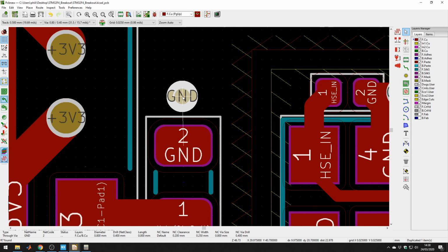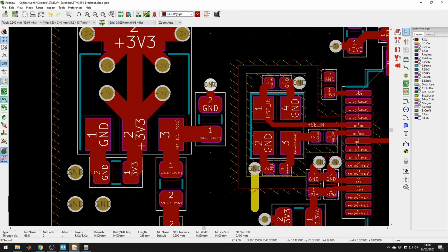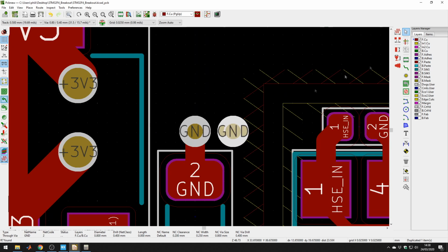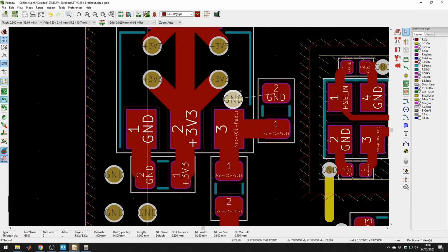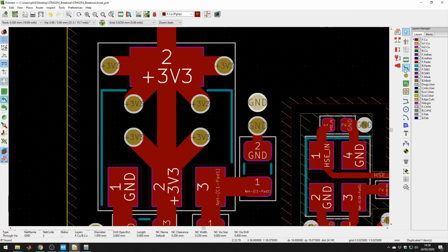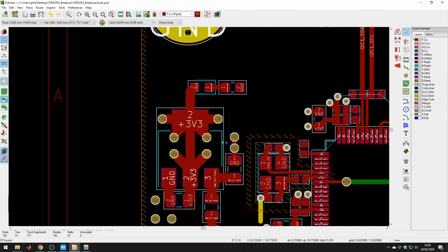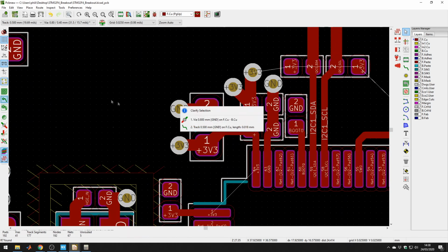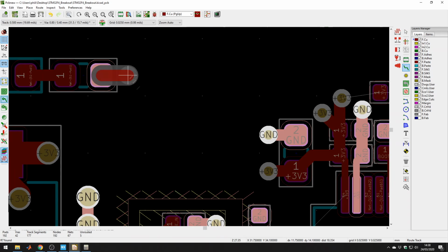Okay, so we're actually pretty close to being done with this. So let's connect that, ground. Actually this one, we'll connect more grounds to it because this is at the regulator. Yeah, actually let's use different wires for this. Vias. I don't know if it's vias or wires. Even if you use them in series like this, it'll still minimize the inductance. Okay. So I'm just duplicating them so I don't always have to reassign the net name.